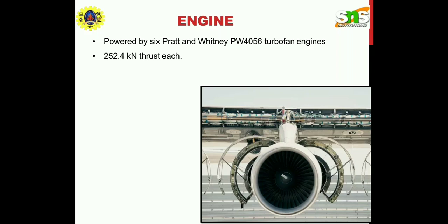Outward flow type increases the energy level of the fluid and vice versa. Due to the continuous changes in direction, several radial stages are generally not used. A centrifugal pump is an example of a radial flow turbo machine. There is also the mixed flow turbo machine, and a Francis turbine is an example.